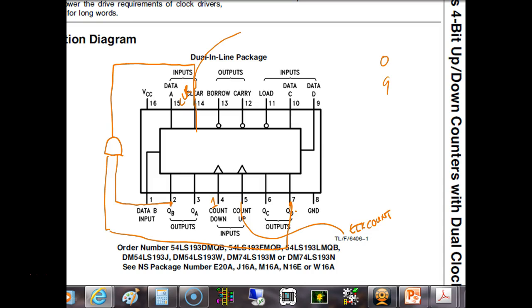Well, programs take time to run. Y'all understand that? So that means none of your software counters could keep up with some of the counts that we have to keep up with today. So PLCs finally realized that. When PLCs first came out, the only counters you had were software counters. And then we got to these encoders, the ones we use to set the speed of a motor. And those are putting out thousands of pulses per second. And those software counters couldn't keep up with it.